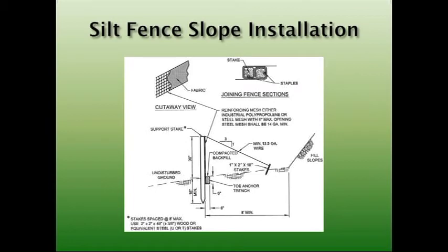This is the wire backed fence, a much stronger fence. I was talking to one of the vendors yesterday, and basically, if you have to put the silt fence up twice, this one pays for itself. Keep that in mind. It also normally has a much longer lifespan than the other.